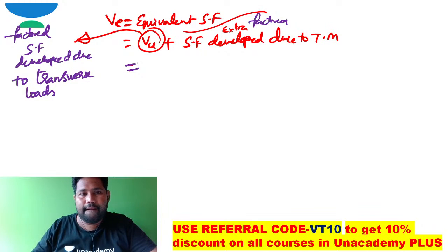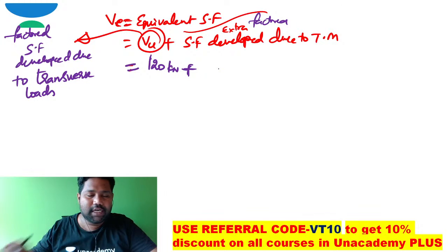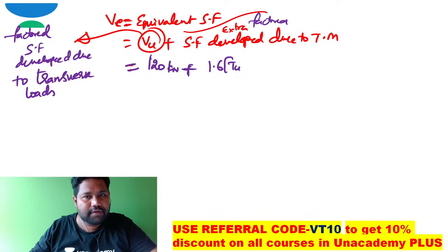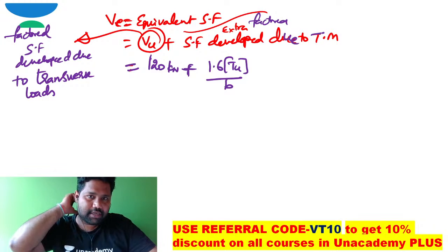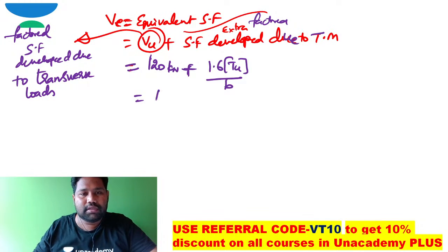Coming to VU, it was given as 120 kilonewton, plus the extra shear force developed due to torsional moment. If you refer to IS 456 2000, for the limit state method, it is given as 1.6 times TU by b. This is the extra factored shear force that has developed due to torsional moment. Is that okay, brother? So in this answer, it is 120 kilonewton plus 1.6 times TU.